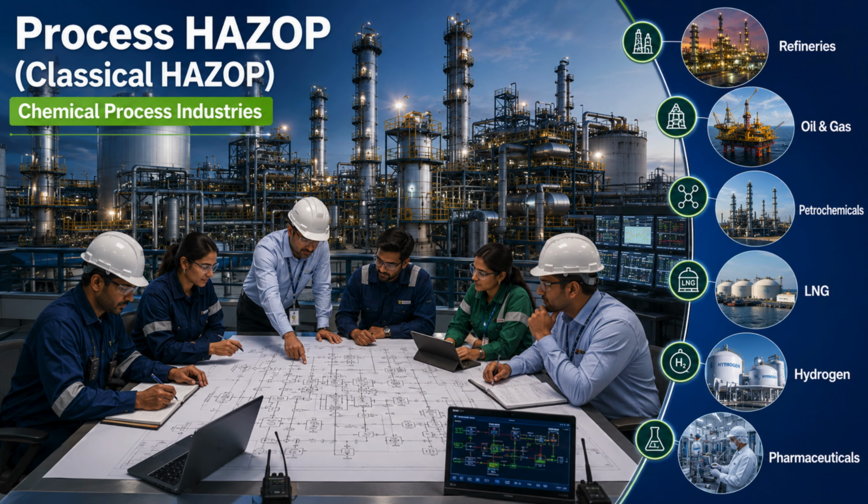It identifies hazards and operability issues caused by deviations from the design intent in chemical process industries such as refineries, petrochemical plants, oil and gas facilities, LNG terminals, hydrogen plants, pharmaceutical industries, and fertilizer plants. Its primary reference standard is IEC 61882-2016, supported by guidelines from OSHA, API, CCPS, and other national process safety regulations.